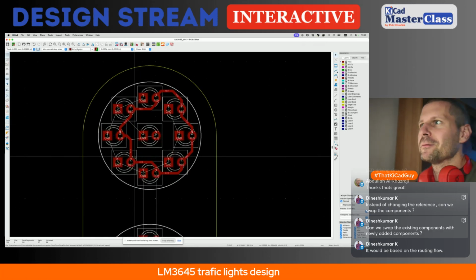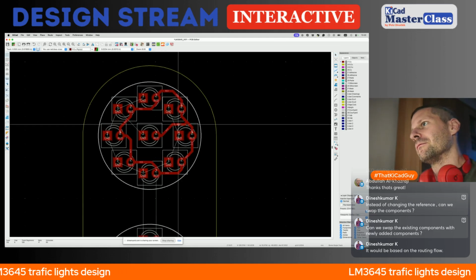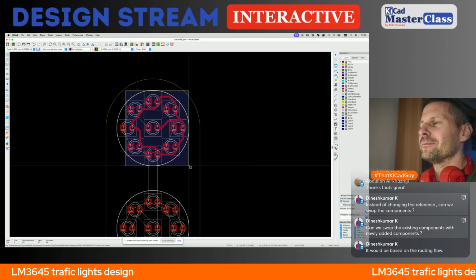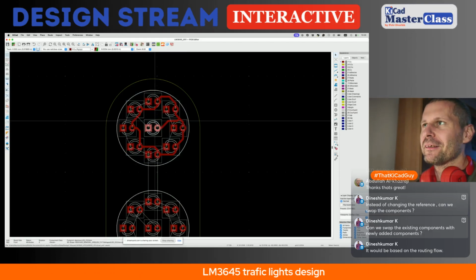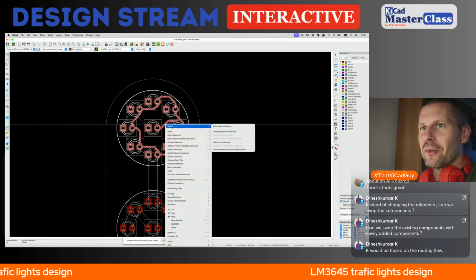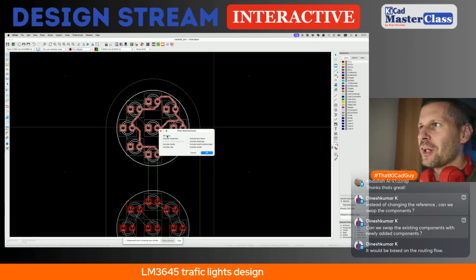It looks like a drunken sailor, but I will show you a trick. I hope it will work. Select the entire area. In the selection, press the mouse right button, filter selected items, uncheck all items, check only tracks.